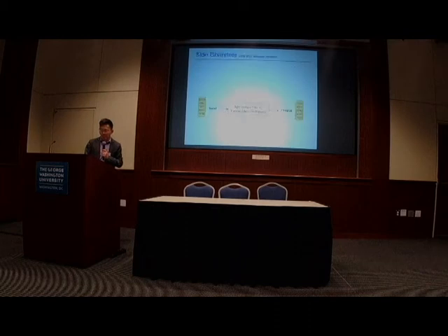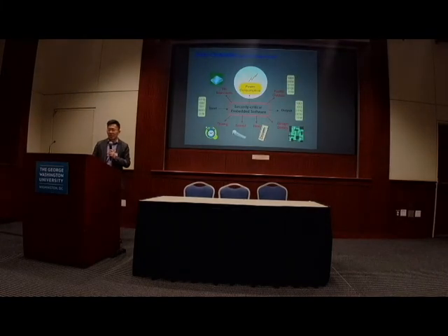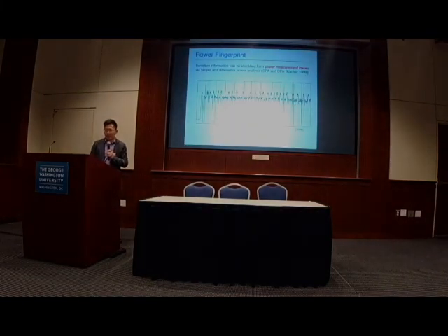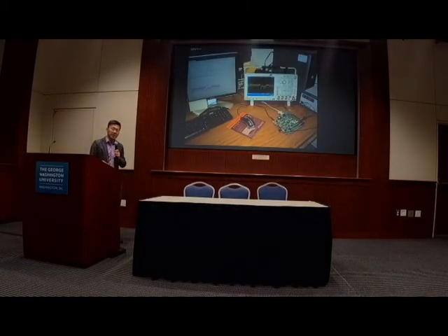So let me be more specific. If we consider the classic, for example, crypto code on smart cards, you have input, you have output, and you have some kind of side channels: power, for example, timing, EM emission, and you have a lot of other architectural-level side channels and fault injections. If you look at the power, in front of this audience, I don't need to go into details because these are all well-known. But you could actually perform this kind of attack.